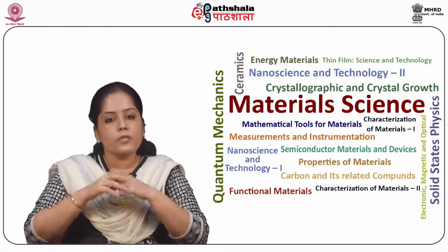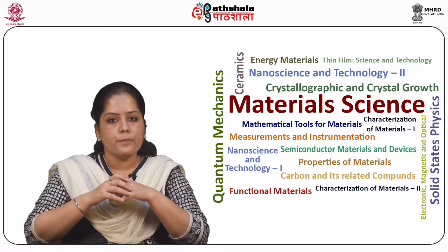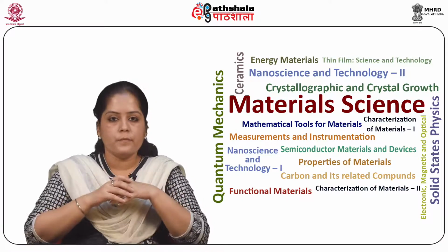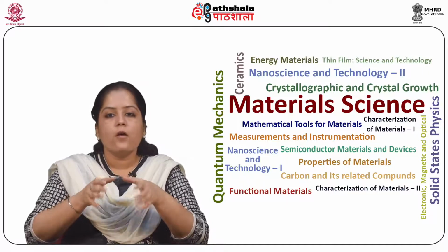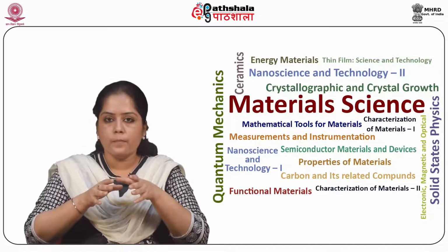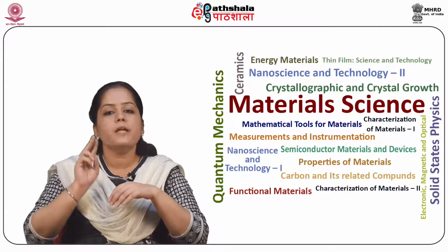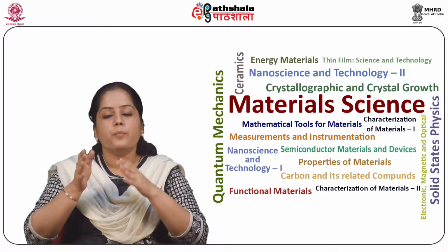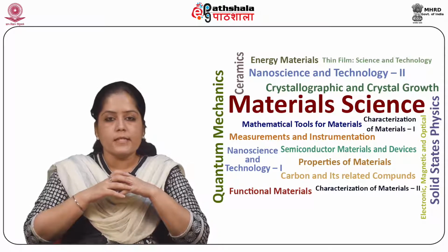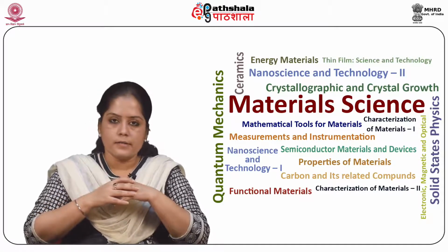In this module, we will see how ceramics fail in a brittle manner. The actual strength is approximately 1/10 to 1/100 of the theoretical strength. This is because of the presence of pre-existing flaws. Two approaches to treat the problem have been discussed. First, the energy balance approach, and second, the mathematical crack approach. The latter yielded a parameter called the stress intensity factor, at the critical value of which fracture occurs.